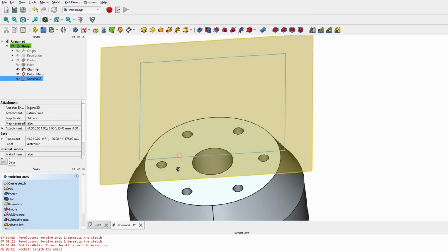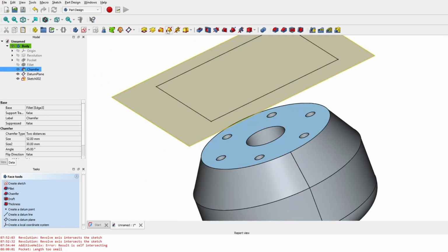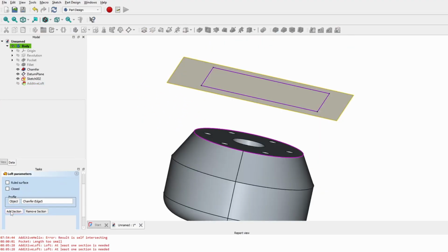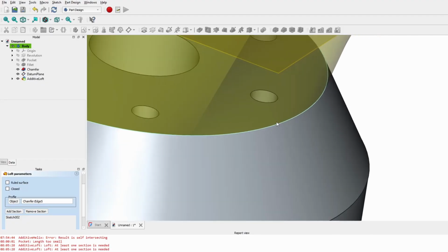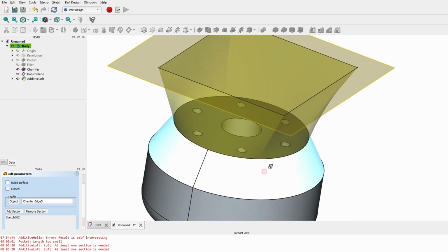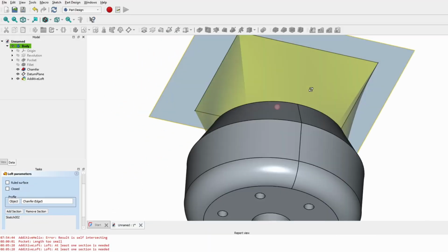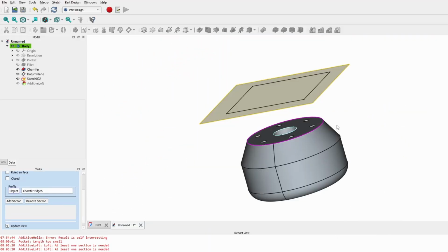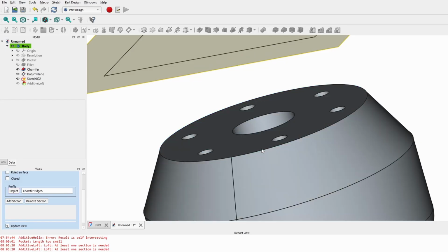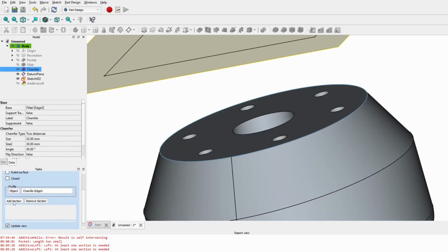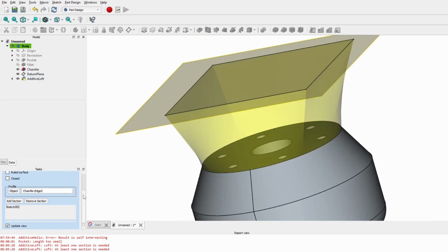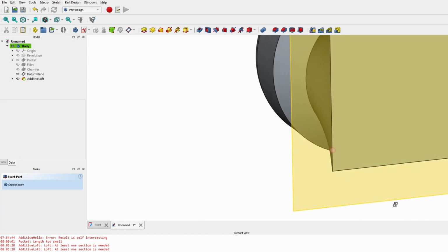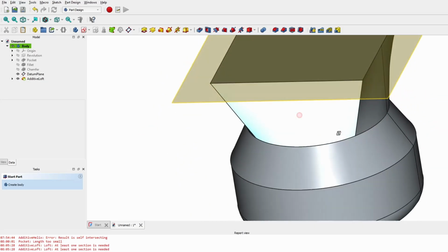The next thing that I want to show is loft. So if we try and create a loft here, add a section like that. You're essentially selecting two shapes right here. So if for some reason we want this circle, the highlighted circle there, to merge with that square or rectangle, then we can do it. We have two 2D shapes. We select both of them. You do sketch 2 right there. You select both of those 2D shapes, and then you can have them merge into each other. The computer figures out how to do that, which is pretty cool.